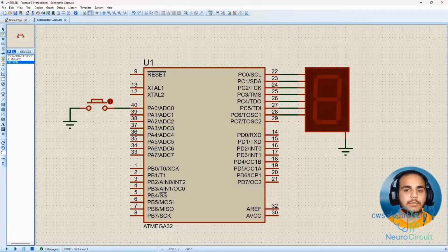And for example, what kind of condition do we set in our code? Now, when one side of our button is connected to ground, it means that every time we press the button, we're applying 0 volts to the pin. In other words, it sets our pin to 0. So in our code, we set this condition. If the pin is 0, it means the button has been pressed.